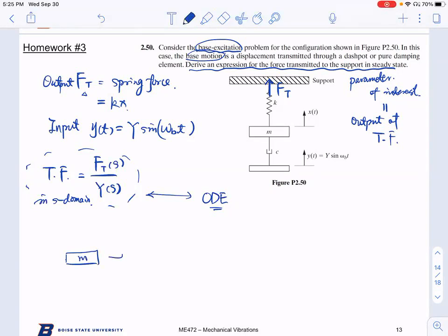So you have a mass moving up, and then you have your spring force. Let's name it Fk. You have your damping force, Fc. So what is your Fk? It is minus kx, right? Is it clear? That means when you have negative displacement, the spring is pushing the mass upward, right? Because we're compressing the spring, so it's negative.